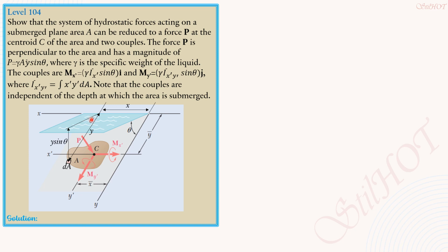Differential force dP is equal to the pressure at this point on the differential area times the differential area. By the way, this is the center of pressure, and the distance of the center of pressure from the y-axis is x sub cp, and its vertical distance from the x-axis is y sub cp as shown. So this is y sub cp and this is x sub cp.